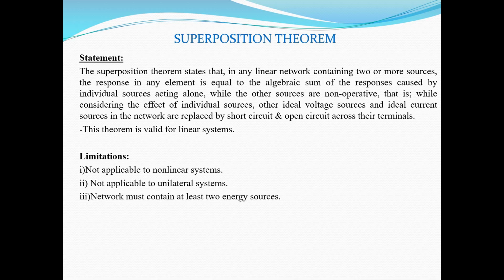In that case, to find out the response of any element, what is the meaning of response of any element? Response of any element means either current flowing through the particular element, meaning resistor, inductor or capacitor in any electrical circuit. So the current flowing through the element or voltage drop across the element or power dissipated by the element is called the response of that element. So response of any element is equal to the response caused by individual sources.